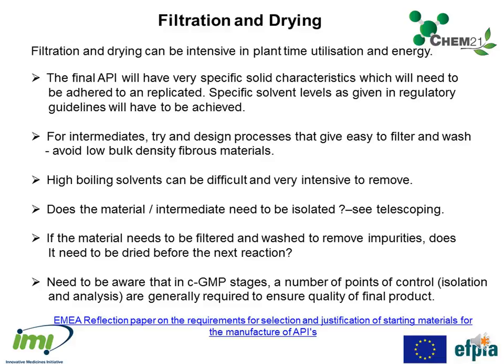If you have a material or intermediate, does it need to be isolated? And we'll talk a bit more about telescoping reactions later. Maybe we don't need to actually isolate that particular intermediate. If the material needs to be filtered and washed to remove impurities, does it need to be dried before the next reaction? So, if there's a few percent of a solvent there, or water, and it's going into the same solvent or a compatible solvent, do you really need to spend time and energy drying it?